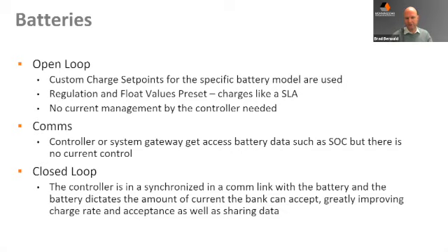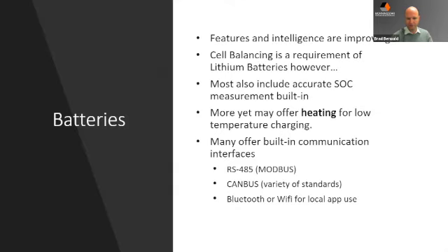And then lastly, with closed loop, in the case of a charge controller or an inverter, the data is not only collected and shared between the products, but there is a link between the products that allows the controller or inverter to work with the battery to know exactly what level of current it wants. If it can actually give it a much higher level of charge, and that battery is telling the controller, "Just don't hold back, give me a 1C rate, I can handle it," then the controller knows that it can do that. So we classify them into those categories.